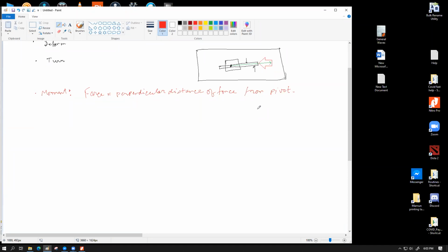All right. So the SI unit for moment is given as Newton meter, whereas the SI unit for work is given in joule. One is given as the force into perpendicular distance. The other one is given as the force into distance in the direction of the force. So there is a sort of direction involvement, two alternative direction involvements for the definition of moment and work done, although they would always come from the product of two similar quantities.